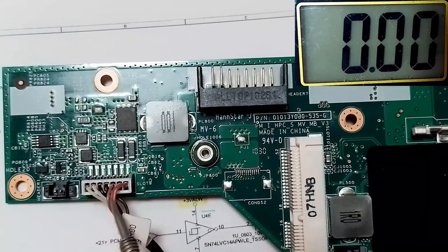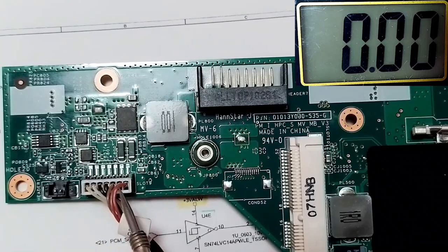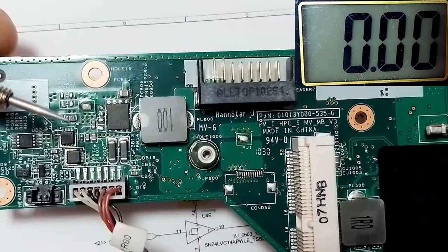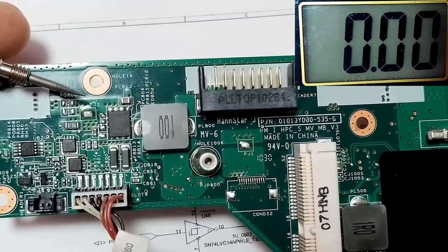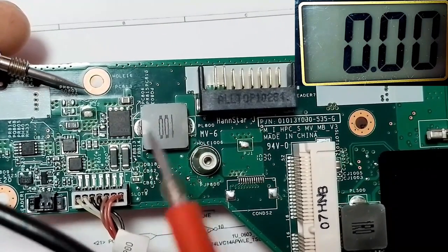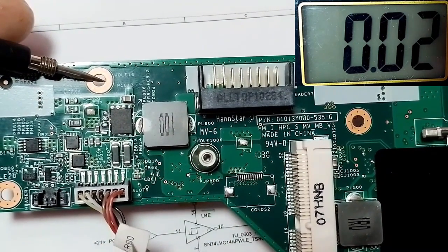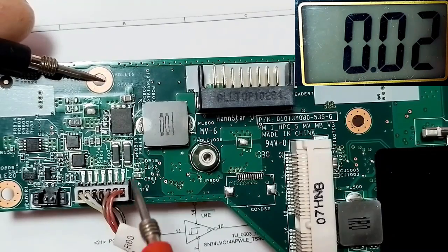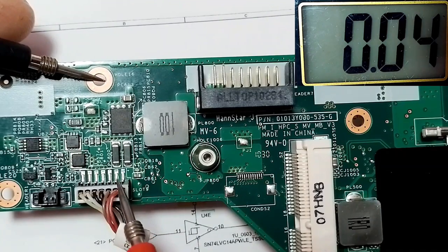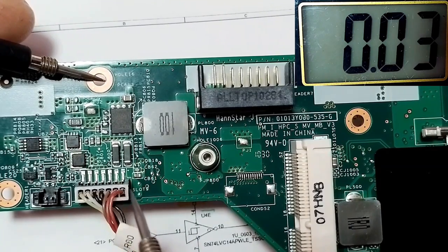So basically this is the power jack cable. Here these 2 red cables mean 19 volts, the positive side, and here we have the ground. So if we measure between ground, as you can see here, and these two red cables or these two terminals, we should get 19 volts on the multimeter.